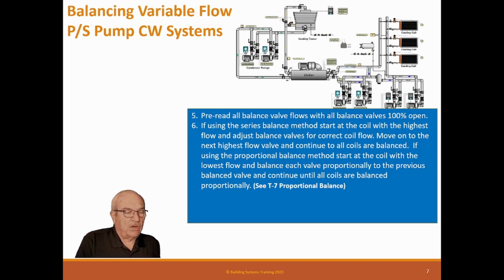So you get the target valve first, and you leave it open, and you go to the second valve, and you balance it down so the two percentages are exactly the same. Then you go to the next one, and you balance it down so that those two are exactly the same.